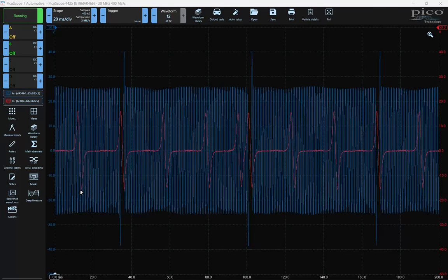So with an oscilloscope, we can determine the relationship of the cam and crank signals and compare those to a known good engine to see if there's a timing issue, a problem with the target, or some outside electrical noise is making its way into the signal. So in this example that's taken from a John Deere level 33 9-liter engine, which is a 6-cylinder, we can see that the cam position sensor output in red and the crank position sensor output is in blue.